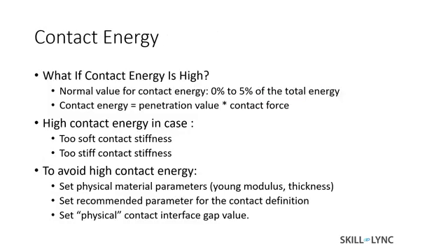Now contact energy. In many of the complex simulations such as these, contact energy happens to be one of the important parameters that needs to be looked at, because suddenly you'll see that in the engine file the energy error is shooting from 1% to 99.9%, and that has many reasons or implications, but one of them can be contact energy.